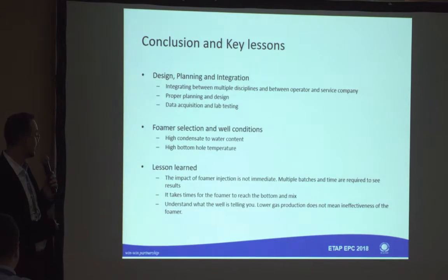And also, the most important thing is to understand what the well is telling you. It's not just from a gas rate, but you have to understand your water gas ratio, your CGR. If you have bottom hole pressure, look at the bottom hole pressure and see how the foamer is impacting you.